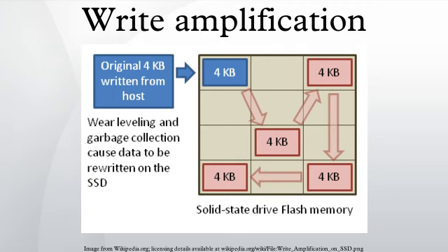Over-provisioning. Over-provisioning is the difference between the physical capacity of the flash memory and the logical capacity presented through the operating system as available for the user. During the garbage collection, wear leveling, and bad block mapping operations on the SSD, the additional space from over-provisioning helps lower the write amplification when the controller writes to the flash memory.